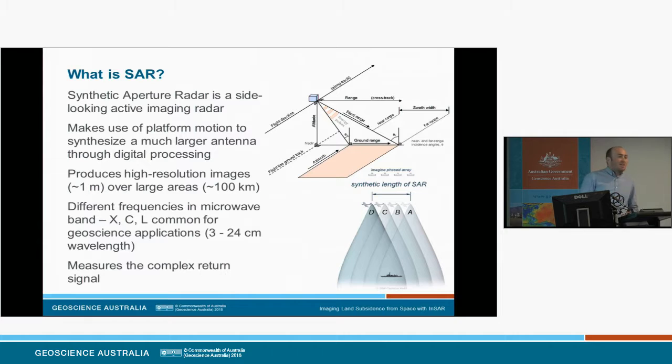The clever thing about the synthetic aperture radar is it synthesizes a much larger antenna than it actually is in physicality. So for any particular target on the ground, it's imaged in the radar for a long period of time as that platform travels in space. And if we look at the Doppler echoes of this target as time progresses, we can do some fancy digital processing and pick out targets with very high spatial resolution.